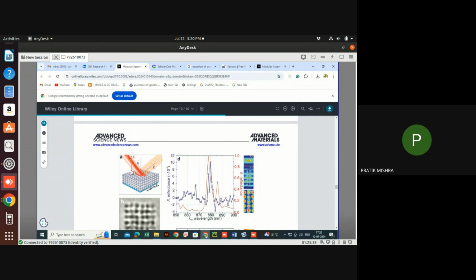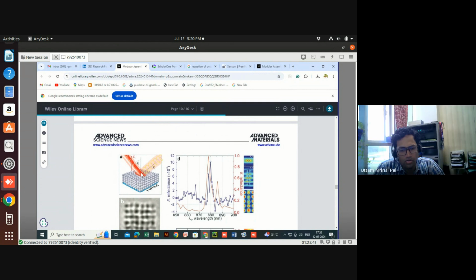In this case, how can they take reflectance by only S21? If you see on the right hand side, that is the actual model. I think that's what they have made. It is some kind of block of geometry that they have created, and from the top they are applying a port condition, and then another port at the bottom. But they are using angle of incidence; that's what they're making from theta. So that's how it needs to be done. Just make the same model that we have made, but give the angle of incidence some finite value, and then first see whether, because of that angle of incidence, there is an angular plane wave or not. All those things you need to see.